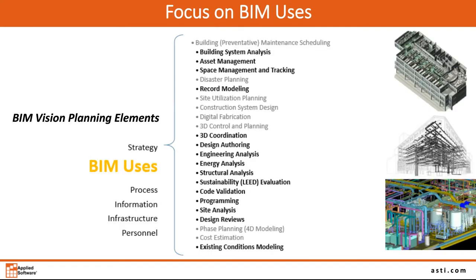Here's another one, and this one I see frequently. People try to bite off more than they can chew. They kind of try to solve world hunger in 1 week. When you initially do your implementation, it's important to focus on, say, 4 or 5 at the most reasonable and attainable BIM goals. Identify 4 or 5 things that you want to accomplish and take advantage of with your initial implementation, and master those, get those things down, and then you can come back and start adding other things to your portfolio of BIM goals, BIM benefits.